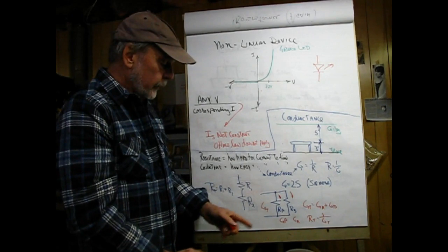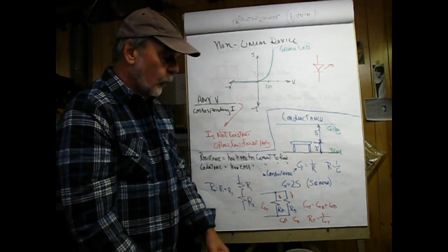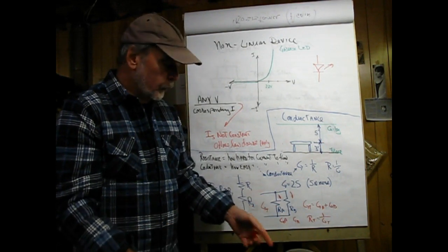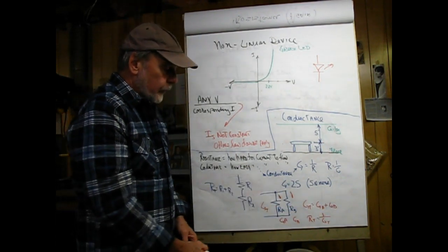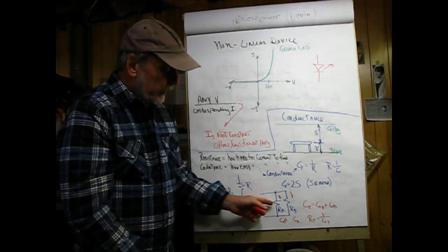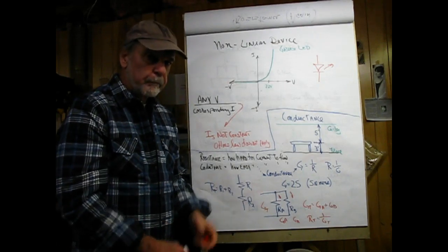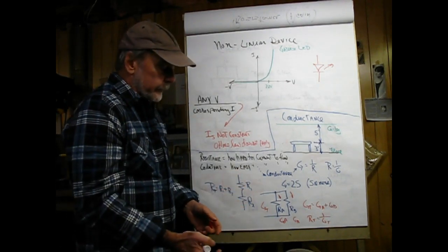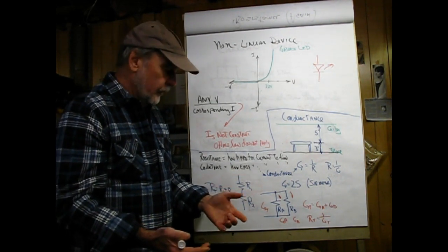And then the total conductance would simply be the sum of the two. If I want to convert that into the total resistance, I just take the reciprocal of it. Now you might say, why do I want to do this? That's a real good question, because we have simplified formulas for doing this directly with resistance that we'll be using. This is to make you aware of conductance because it comes in handy sometimes.